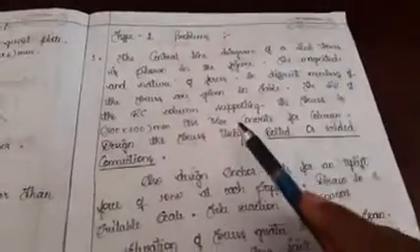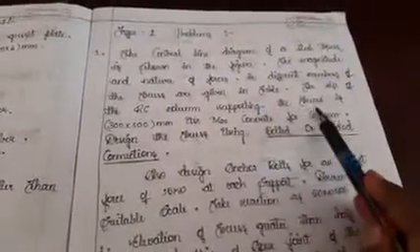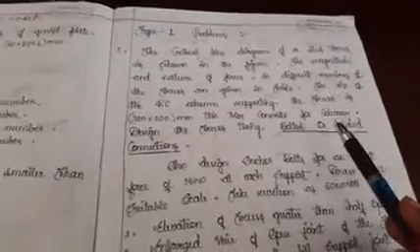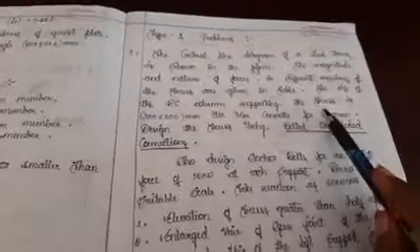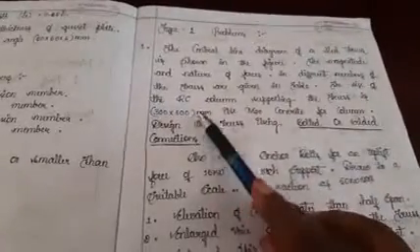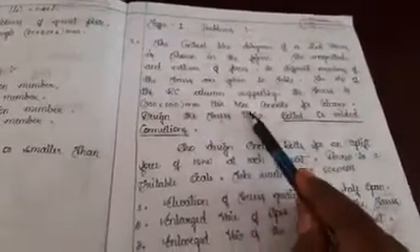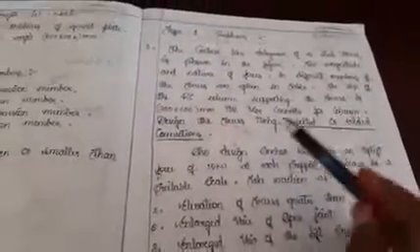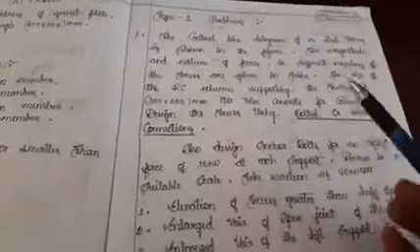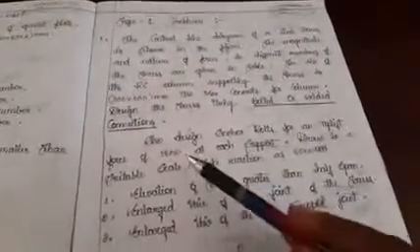The size of the RC column supporting the truss, because the truss stands on the column, right? The RC column size is 300 mm by 300 mm, they are saying. And f_ck, that is the grade of the concrete, is M20 for the column. Design the truss using bolted or welded connection, and they have given a force also.